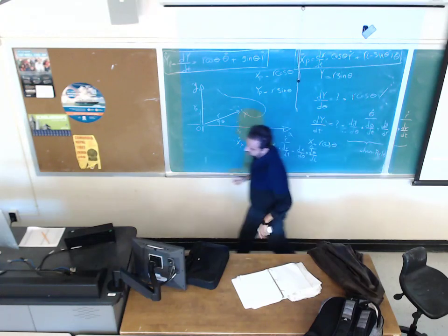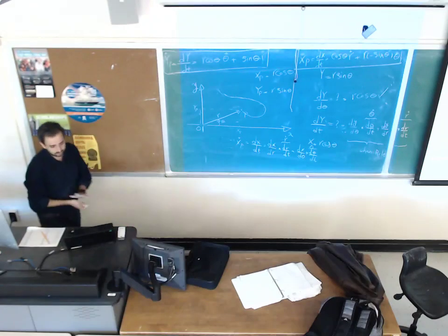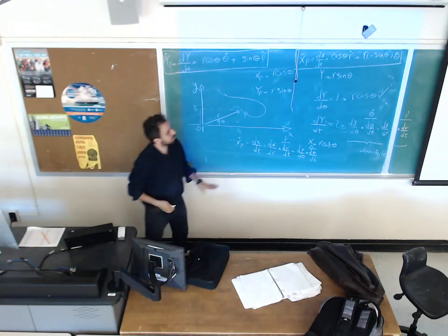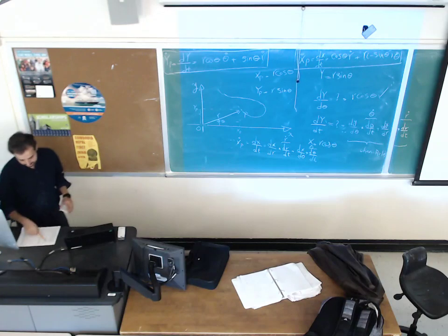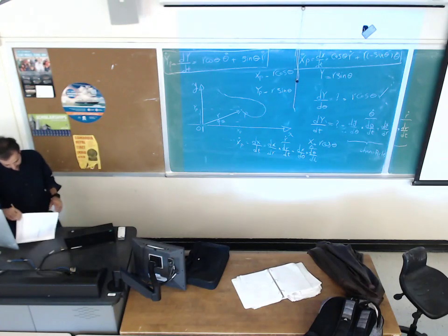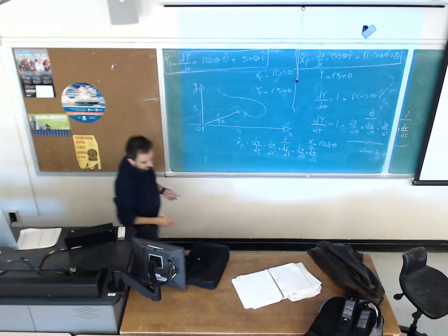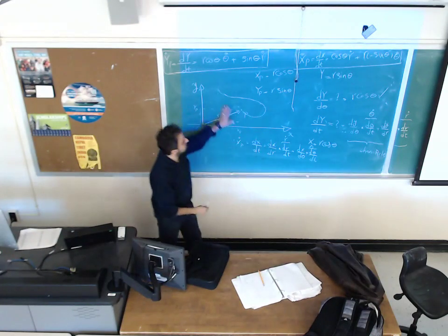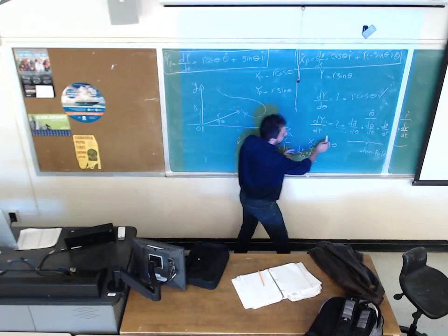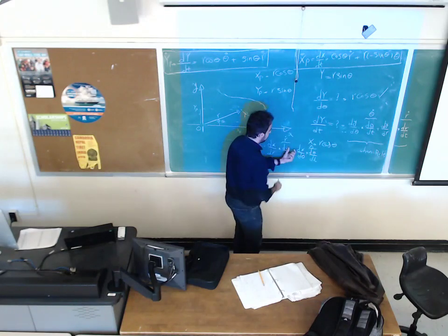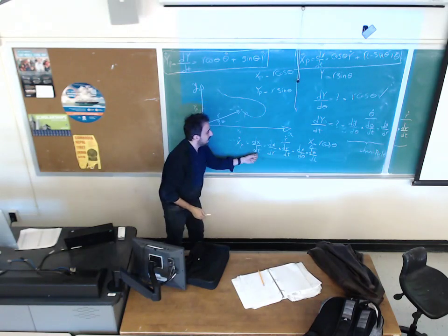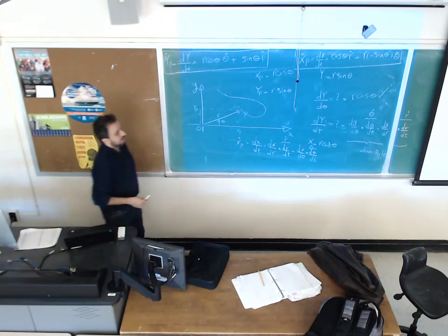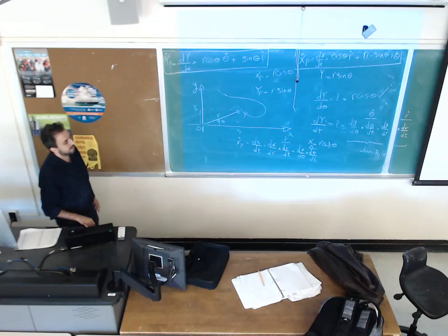And this is the x component of velocity of point P. Alright, the key point here was using the chain rule when the time variable doesn't show up in the x and y functions.